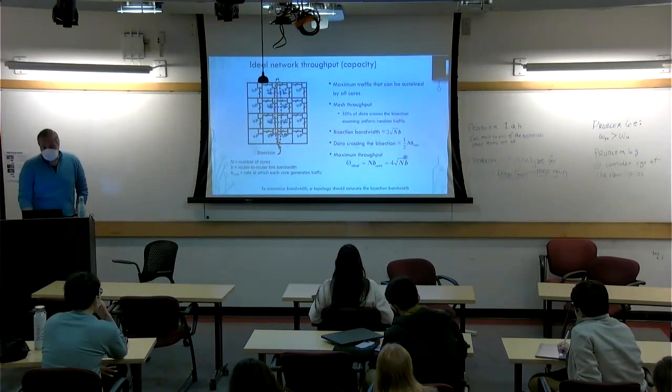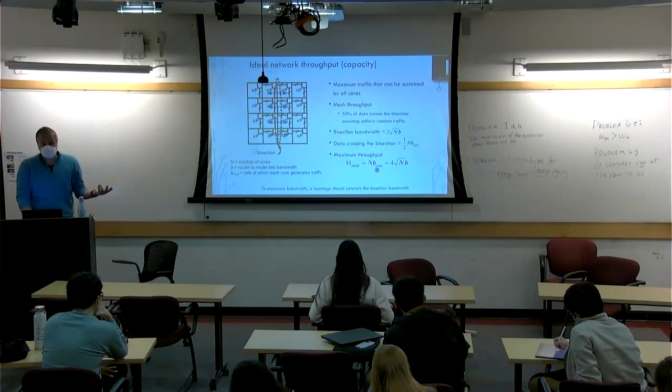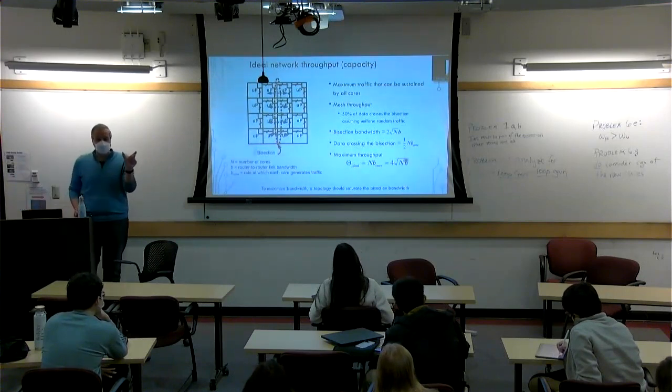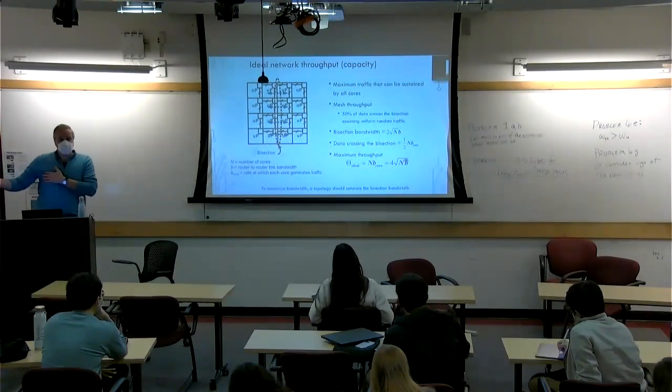Now I can size my channels, right? If I have a desired injection throughput, b core, I have the number of cores. For this topology, I can select b, which is the width of the wires that I have between the two routers, right? And see, does that make sense? If it doesn't make sense, probably need to go change the topology, right?